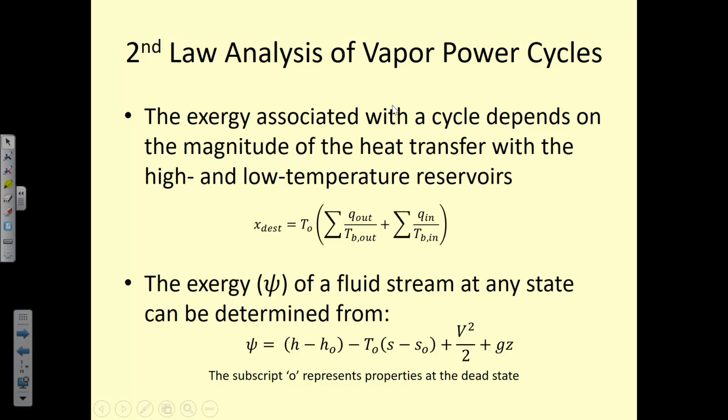So the exergy associated with the whole cycle itself depends on just the initial and the final state, which is the same state, which means that we're only considering the exergy destruction due to the external implications of the cycle. So because our fluid returns to its original state, its entropy does not change. It changes throughout the cycle, but the overall view of the cycle is that it's the same. So we're just looking at the heat transfer with the environment when we consider the whole cycle together to determine the exergy destruction.